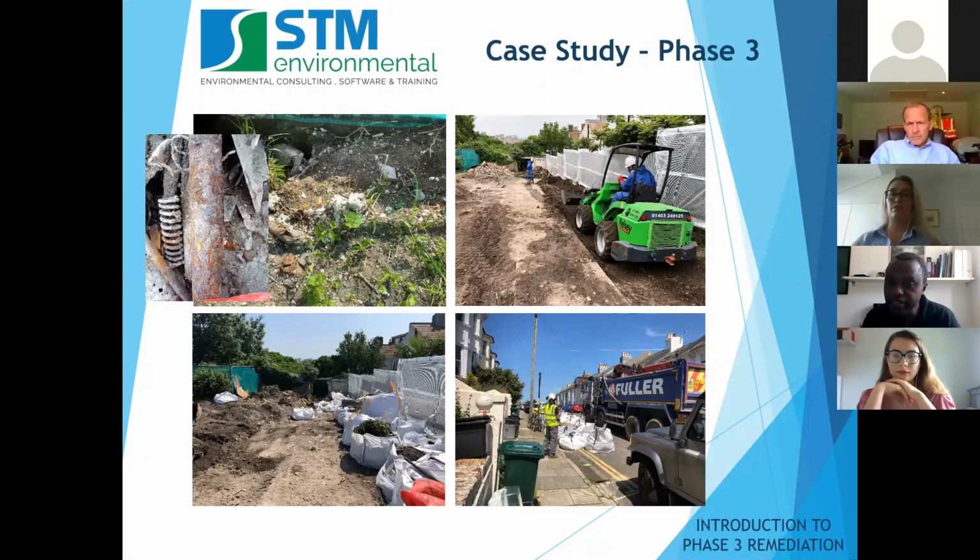We then had to get in a licensed asbestos contractor. We had to manage the neighbours who were, understandably, very worried about all this excavation going on in their backyard. We had to bring in air quality monitoring just to make sure we weren't releasing asbestos fibres into the air. That was done by continuously damping down the soils as we were excavating. Just being very, very careful, and obviously protecting our own health and safety at the same time as we were removing all this soil.